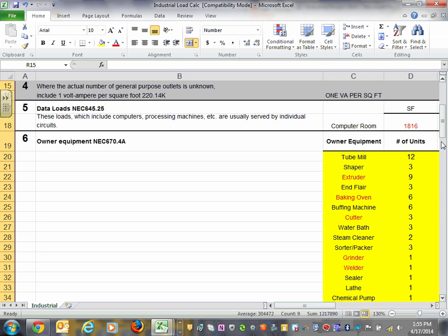Mine, when I did it 10 years ago, it used to be 50 watts per square foot. Now they went way higher than that when they designed the data center. Yeah, 100 and 200, but they're moving towards racks now because it doesn't matter what the square footage of the area is. Give me how many racks. So we have 50 racks in this room, multiplied by 5 kW, and that will give you a rough idea of what your sizing of your system is. Okay, that makes sense? Okay, so that's your data.